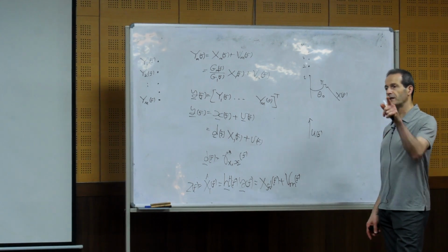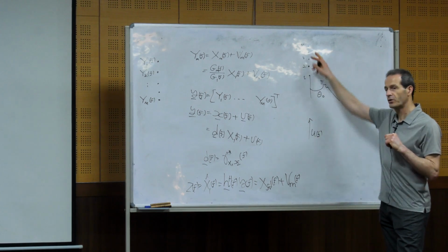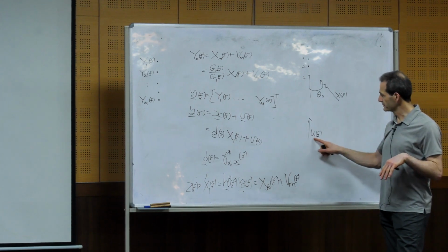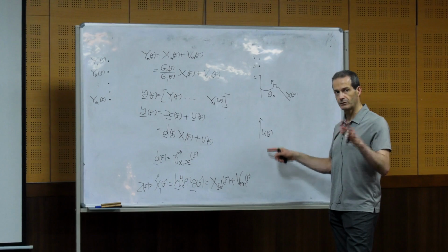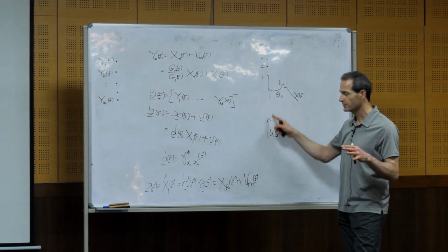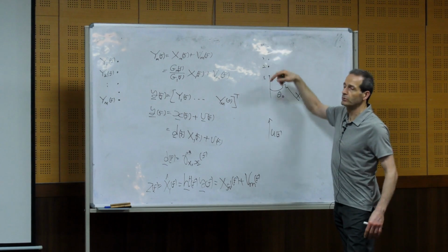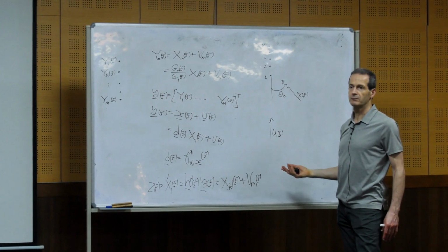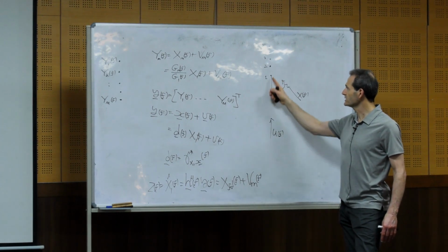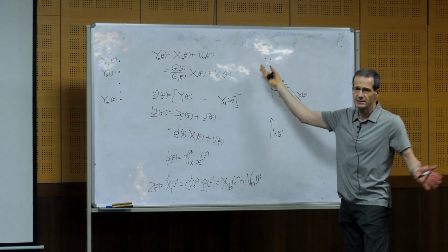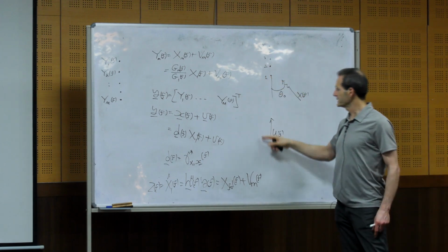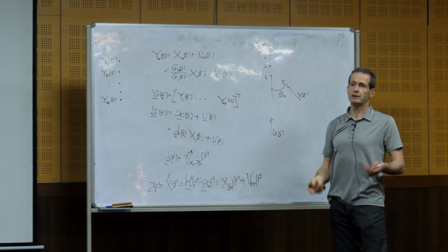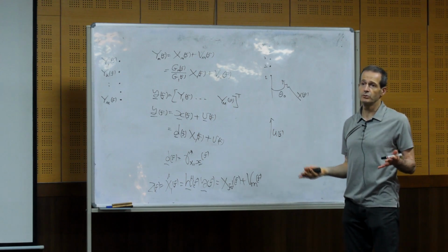Okay, so you said no, but I remind you, I said that we also have thermal noise. Compared to the directional noise component that comes from this direction, we don't improve. If we add more sensors, we cannot reduce this more efficiently because they come from the same direction, so one sensor or multiple sensors give the same performance regarding these noise components. But regarding the thermal noise, of course, we can reduce it to some degree.